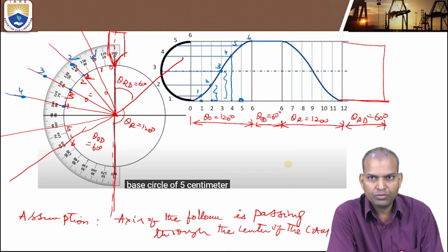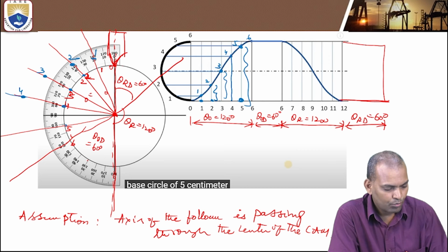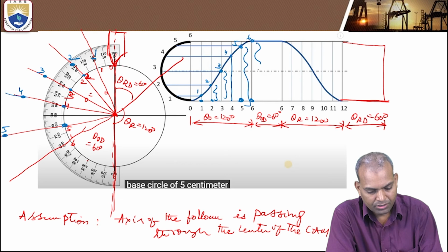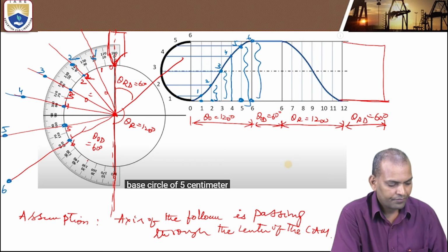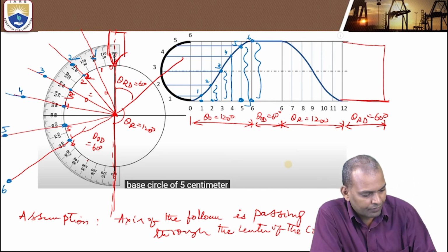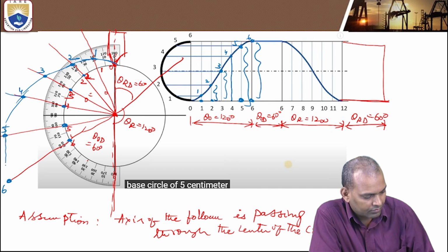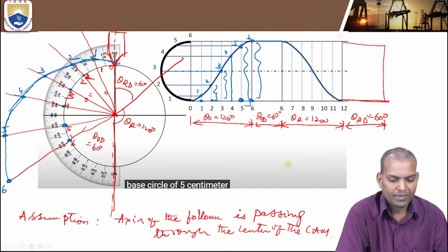Again from point 5 to, on the diagram, SHM diagram, to 5. This distance. Point 5 to 5. Next point 6 to 6. This distance. This is the center 6. Length is 6. Okay. Join this curve with a smooth sketch with a pencil. This is the cam profile during outward stroke.